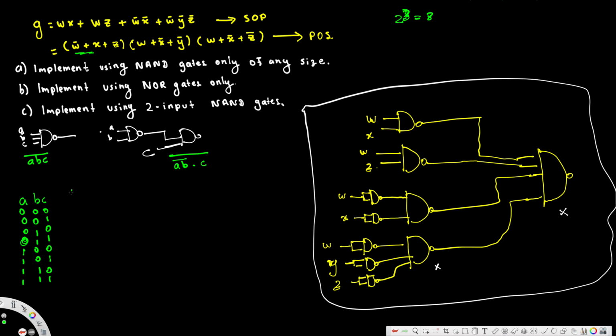Here, first we are going to see the truth table for (ABC)'. ABC whole bar means we multiply first, then take the complement of that. When you multiply, if you have a 0, the whole thing is going to be 0. So wherever we have a 0, the product is 0, and if we complement that, we get a 1. So wherever we have a 0, the output is going to be 1. Wherever all of them are 1, the product is 1, like the AND gate, but if you complement that, it's going to be 0. So this is for ABC.